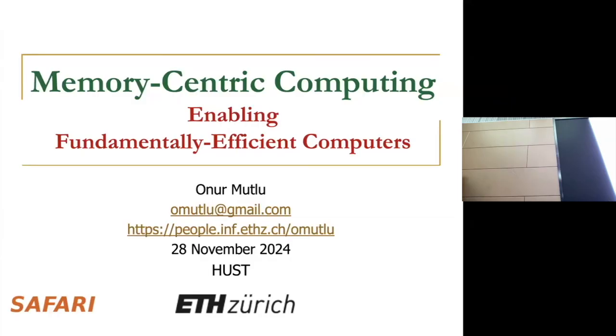If we take a step back, today capacity is everything, and then there are computation processors where capacity is almost nothing, whereas computation is everything. Right? We need to find a balance where we design a memory chip that has some computation capability without a whole lot of cost. And we need to explore that space right now. And I believe there are ways of doing that. For example, the processing using memory approach is one way, but so is adding small functions to the DRAM chip.